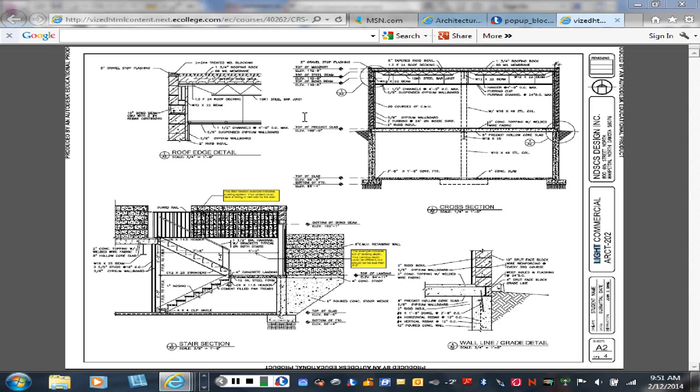So for the purpose of drawing your floor plan, let's assume at this point that our main level is going to be at 12 foot 8. That'll give us our roughly 9-foot ceiling height. And if some of you may have decided to raise the center part of the building or even go to a 2-story, you'll have to create a higher level, obviously, right? So let's go back and look at our plan a little bit.